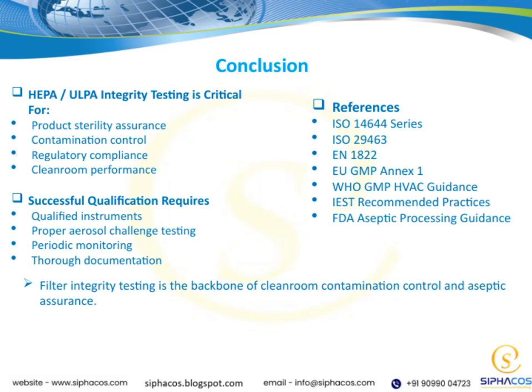And finally, thorough documentation of all testing activities provides traceability and compliance. In essence, integrity testing isn't just a one-time task. It's an ongoing process that underpins the safety and effectiveness of your cleanroom environment. It's about making sure that your filtration system continues to perform at the highest standard, protecting both product quality and patient safety.